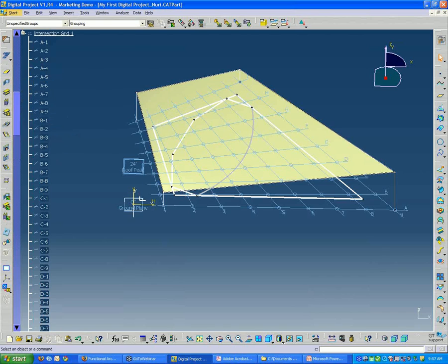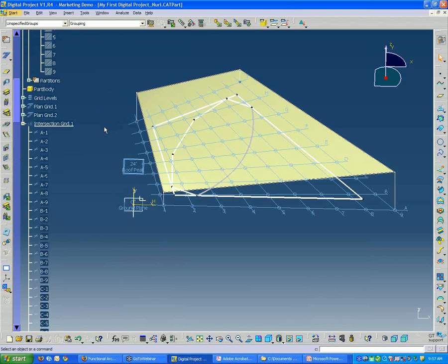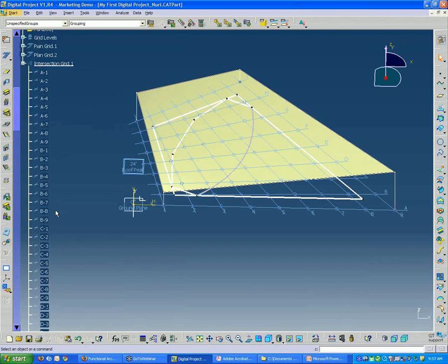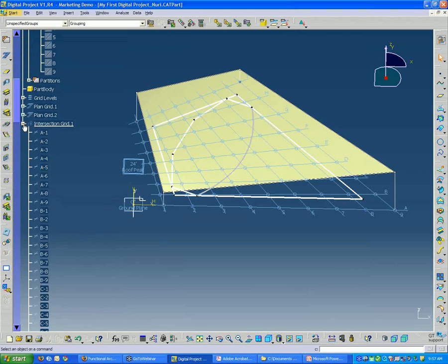And this is a very important and very powerful tool for BIM modeling, because not only are these intersection points now quickly defined, but you can easily locate them. And if you use these elements for columns and to locate different objects, you can instantly know, based on this point, where that column is located. It refers to the point that it was created from.